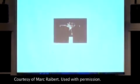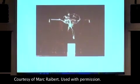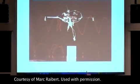Here we go. So this little robot, you can see that's tracing its foot. This up here is tracing its center of mass, and you see how the center of mass actually compresses right above the foot. And so that's what you expect here. It lands and it squishes down. So instead of when you're walking and you vault over this leg, like you think about that rimless wheel, center of mass rolls up over its foot.